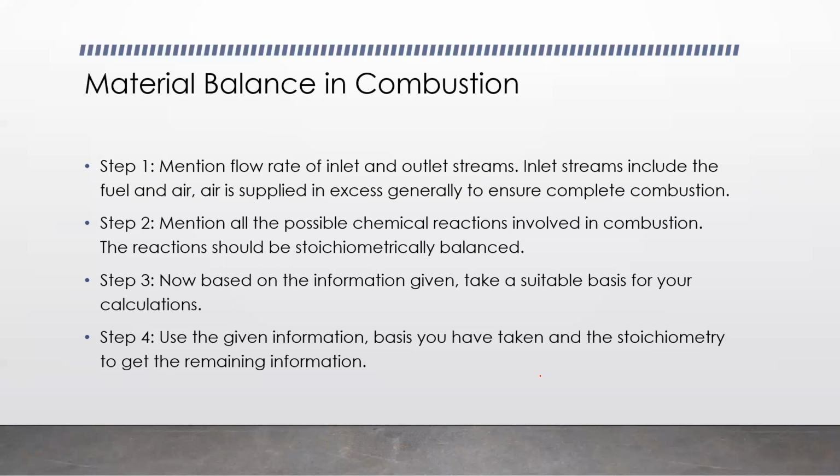All right, remember one thing, although over here in combustion there is a concept of excess air. So we discussed, right, percentage excess. So here we basically supply air in excess because we need to ensure that the combustion is complete.